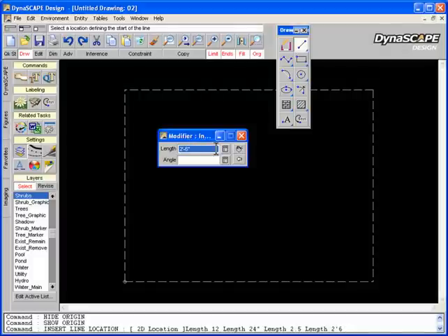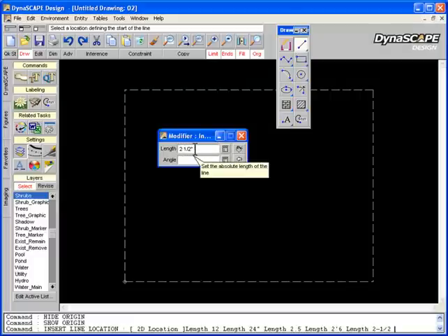If you wish to add fractions of an inch to a value, you do it this way. Type in your inches, and if you're using inches, you don't need to use the inch symbol. All you need to use is a hyphen, and then whatever fraction you wish to use. If it's half an inch, you go 2-1/2, and it will know when you hit enter or spacebar that you want to insert a 2.5 inch value. So entering fractions, you can be as accurate as you like.